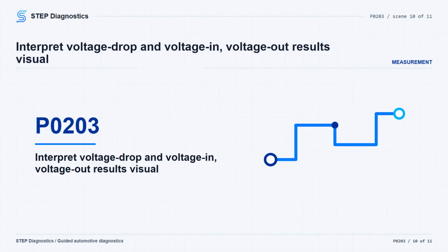For a voltage drop measurement, put the voltmeter across the beginning and end of the suspect part of the circuit. Operate the circuit, or at least attempt to operate it, so power is available to flow. Keep voltmeter polarity in the direction of conventional current flow. A 0 volt reading means the voltmeter connection is bad or the component isn't turning on. A small amount of voltage is normal circuit loss. In 12-volt circuits, normal loss is usually less than half a volt, and expected less than 5% of circuit operating voltage. Voltage greater than half a volt indicates abnormal voltage loss from high resistance in wiring or connectors.